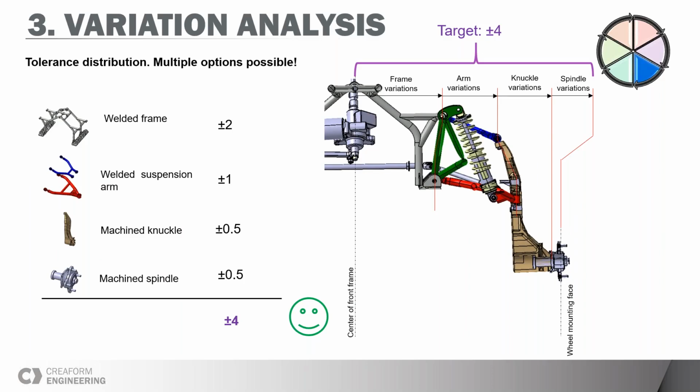The goal here is not to define the tightest tolerance and try to meet the target at all costs. We just want to see if the design can meet the target with standard manufacturing requirements. Putting super tight requirements on paper that will be impossible to achieve in real life won't serve you any good at this point. So what we'll want to do is put a realistic value for each of them according to their manufacturing capability. The goal is to get a value that represents as closely as possible what you will actually get in real life.